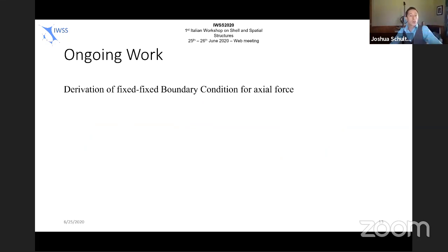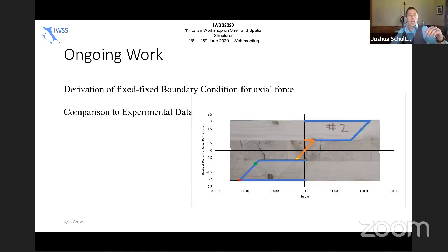Now what we're doing is we're taking those series of relatively complicated closed form solutions and we're doing a series of best fits so designers can kind of plug and chug through those. And then we have just gobs of 3, 5, and 7-ply experimental data that we've been fitting to make sure that we have accuracy in our results. So with that, what we're going to do is we're going to deliver those best fit design equations for actual designers using that 5-ply model.